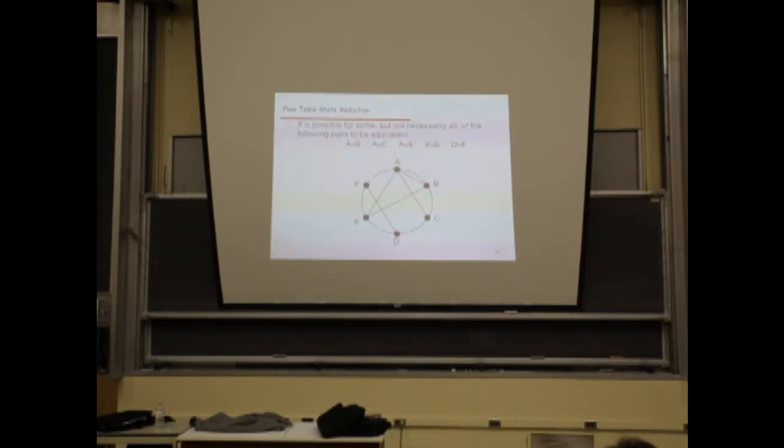So you can tell that I can have A, E, and B together, which means C is going to be left alone, and F and D can be combined together. As you can see, A, B, E, and D and F. C is going to be a lonely state on its own. It's not going to be combined with any other one.